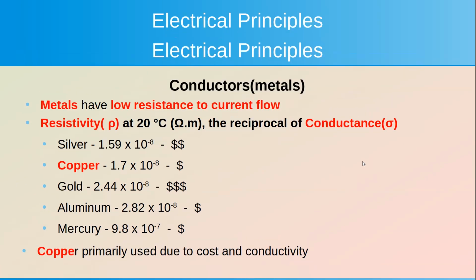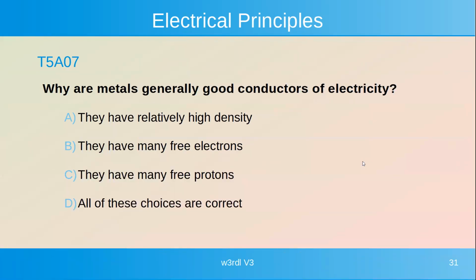Another big advantage with aluminum, especially when you get up into 500 MCM and the larger sizes, is it's something that you can take and hand turn and bend. And when you get up into copper in that size, it takes a hydraulic bender to bend that wire.